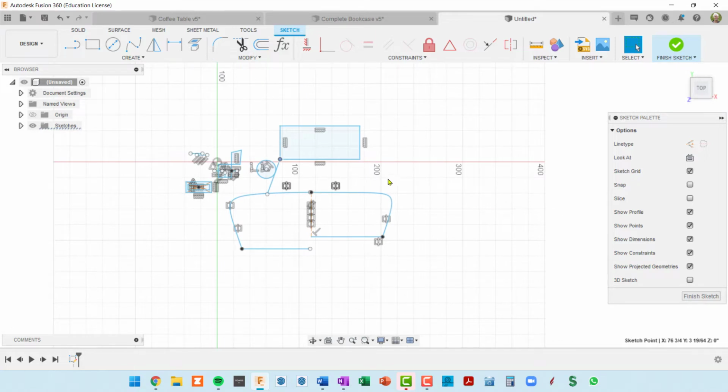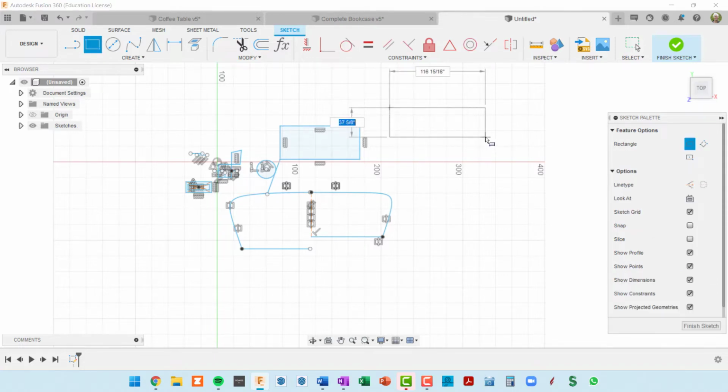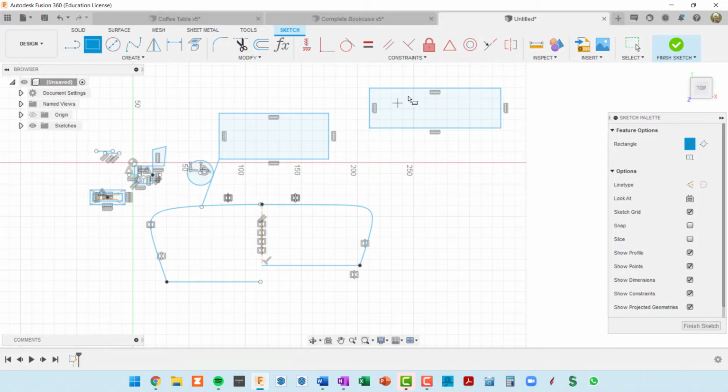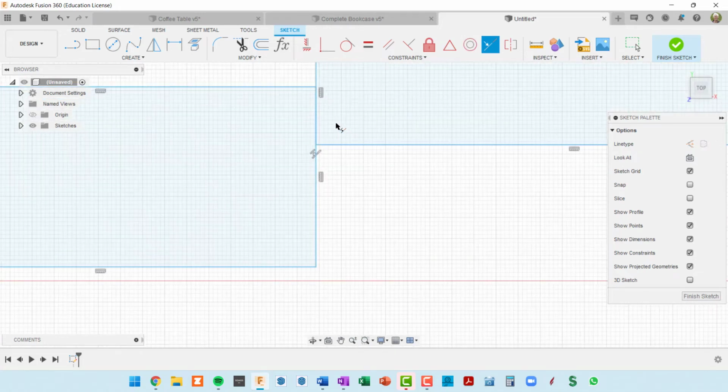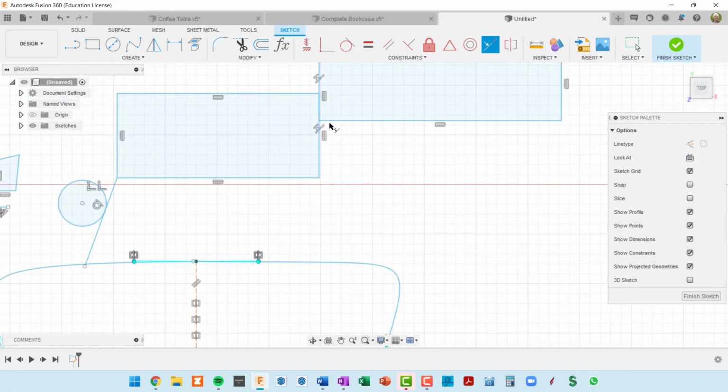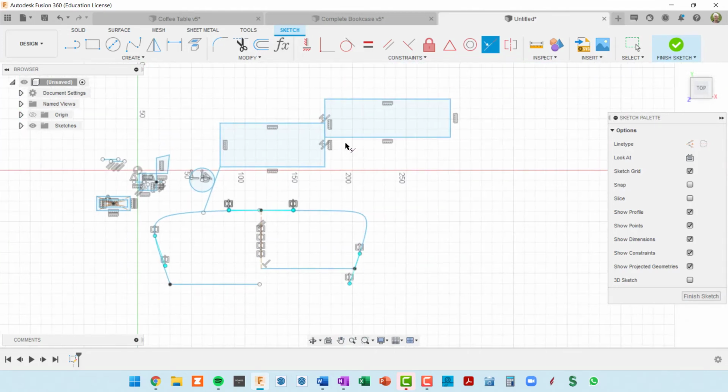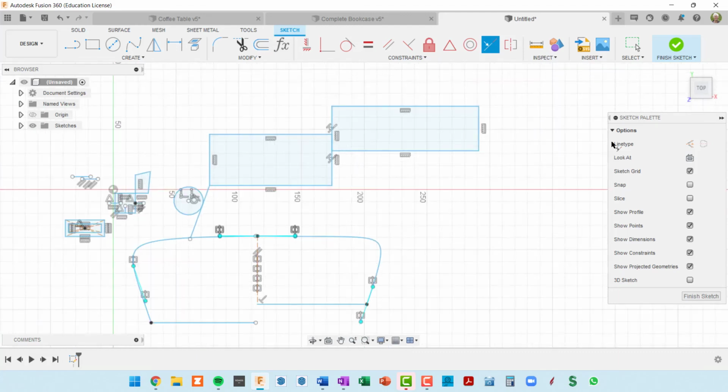But you will see, a lot of times if you watch other Fusion videos, you will see guys who want a rectangle to be in a certain spot, and they will draw that rectangle away from the spot and then say something like, well, now I'm going to impose a collinear constraint, for instance, right here, and say, okay, this line is going to be collinear with this line, and now the sketch constraint is imposed. Whereas if you tried to do this by hovering over it, sometimes you get the right constraint, but sometimes it mistakenly puts in something that you didn't want. So that's an intro anyway to sketch constraints.